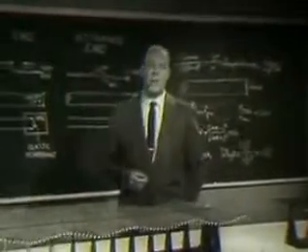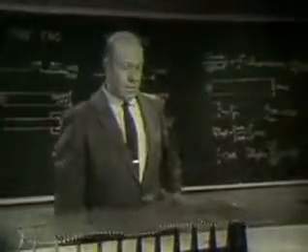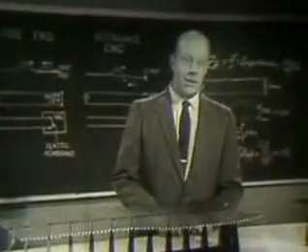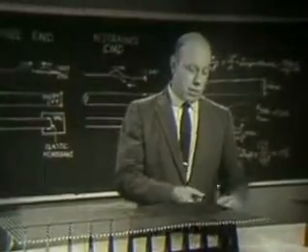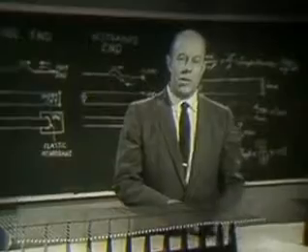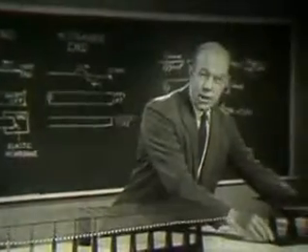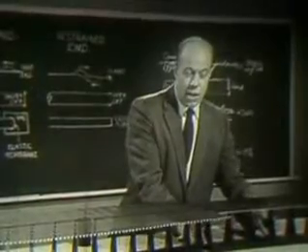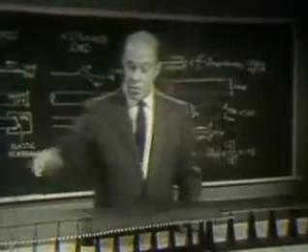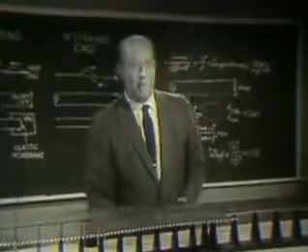Now, let me develop for you another idea. Waves are partly reflected not only at mismatched terminations, but also at places where the impedance of the transmission medium changes abruptly. Suppose I connect these two wave machines end to end. Together, they give me a single transmission line made up of two pieces having different impedances.